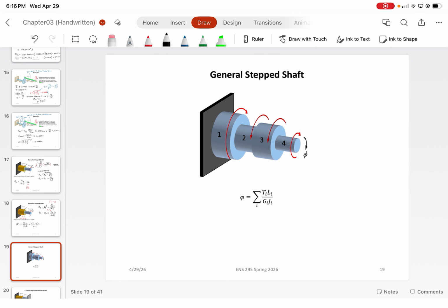So it's whatever shaft or component of a shaft you're interested in, because it could technically be one shaft of all the same material, but if you have several torques applied, it would obviously discretize that block accordingly. So it's synonymous to saying delta is equal to the sum of Ni Li over Ei Ai, for i equals 1 to n. Make sense? So it's very synonymous to what we saw at the very beginning of the semester.